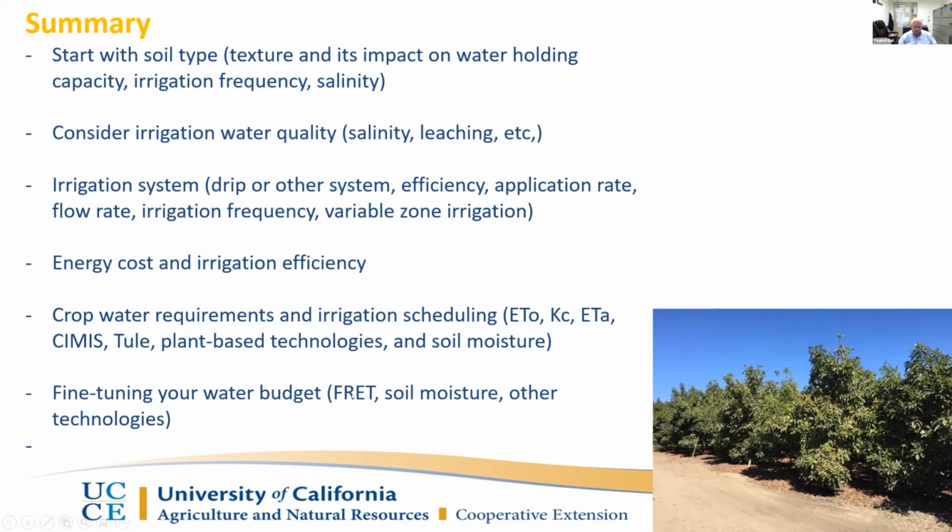And we have newer technologies that I think Daniele will talk about, which is basically forecast ET. Now I can look at ET over the last week, but now we have the technology in such a way that I can predict ET for the next week or for the next 10 days. It's very similar to predicting the temperature for the next few days. On your phone, you could see what the temperature is going to be over the next week or so. We can do the same thing with reference evapotranspiration.